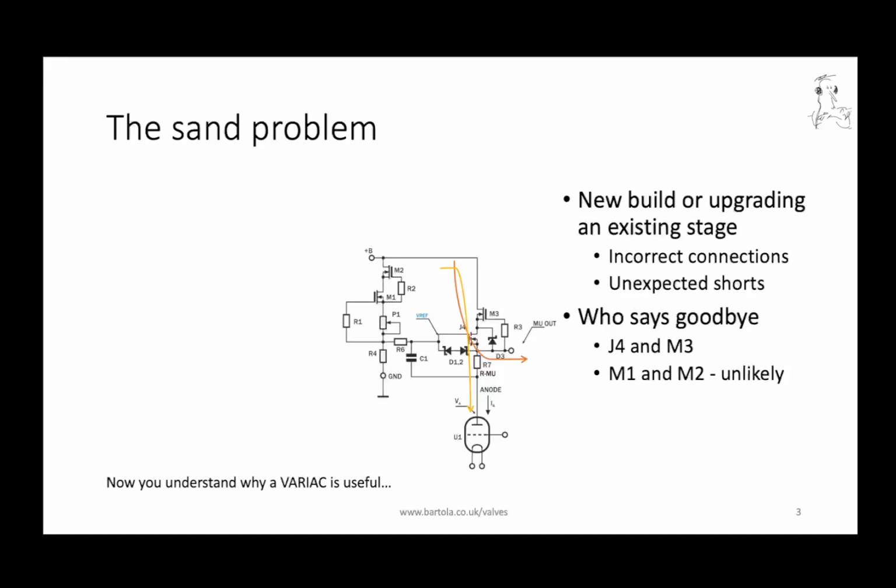But for the sake of simplicity, and for people who are not familiar with this circuit, I'm going to explain it very briefly. On this circuit, there is a constant current source, CCS, on the left, which is formed by the MOSFETs M1 and M2. That cascaded pair provides a constant current through the resistor R4, which generates a reference voltage.